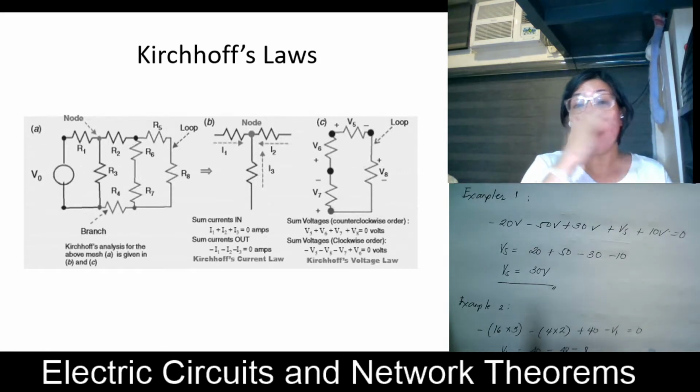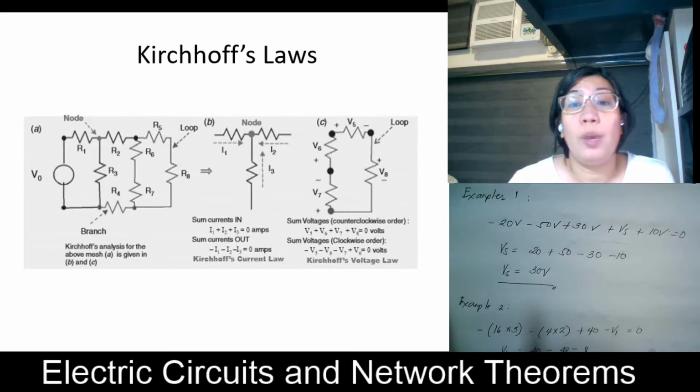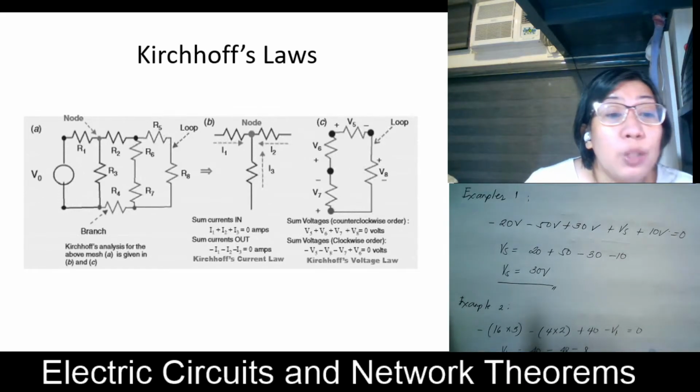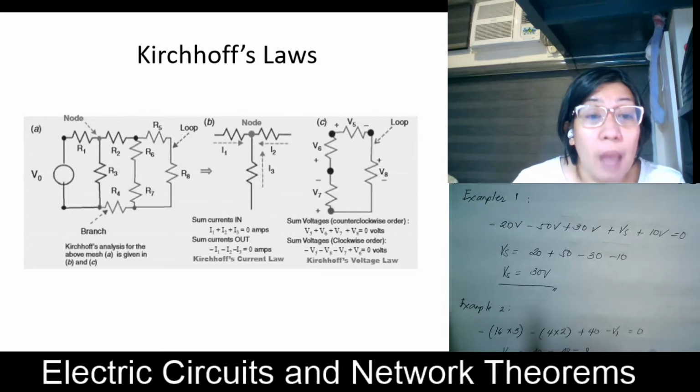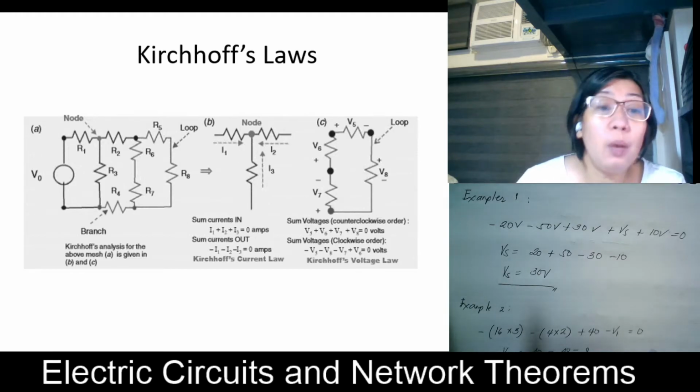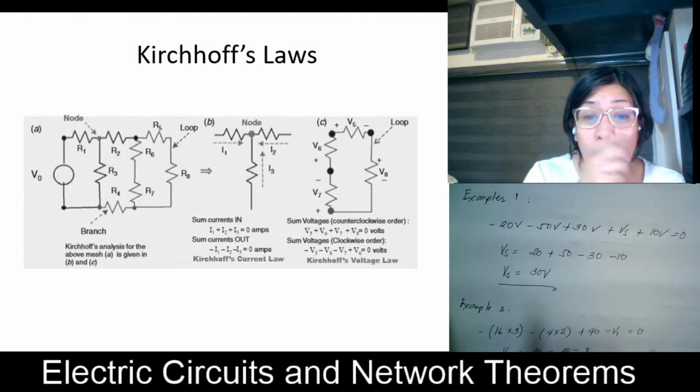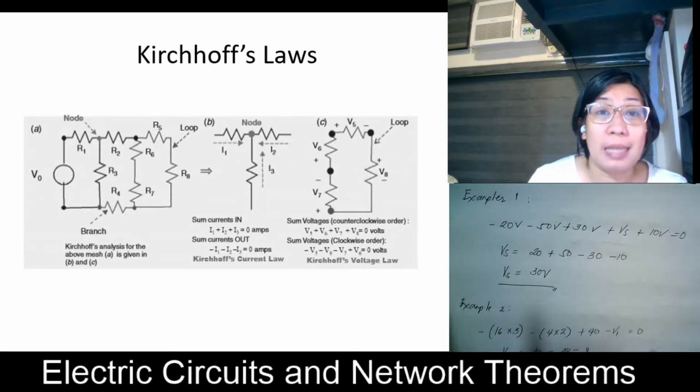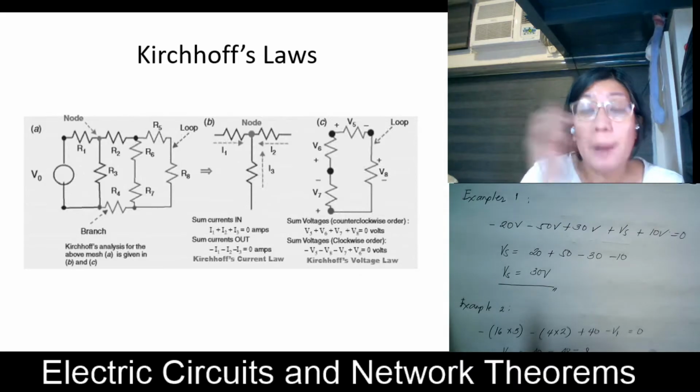So we have here Kirchhoff's laws. Okay? So we have here your branch. The basis of this law is that if we start from a particular junction and go around the mesh till we come back to the starting point, then we must be at the same potential with which we started. So all sources of EMFs met on the way must necessarily be equal to the voltage drops in the resistance. Every voltage from the beginning is given its proper sign, so it's either positive or negative.